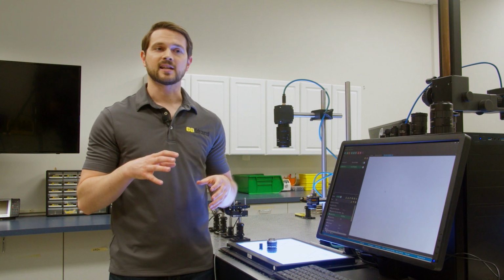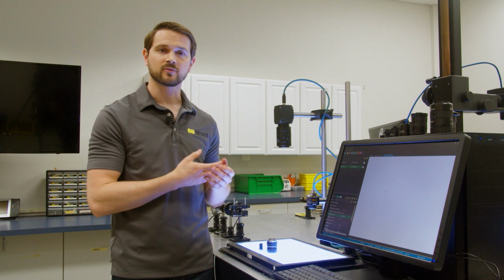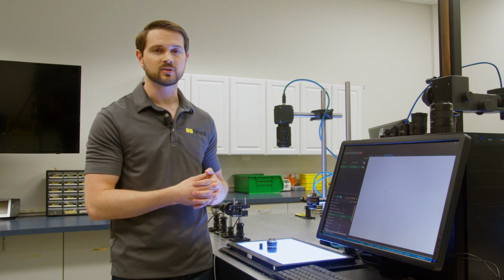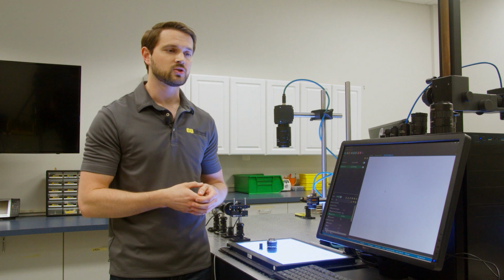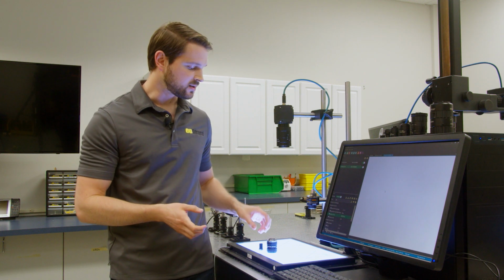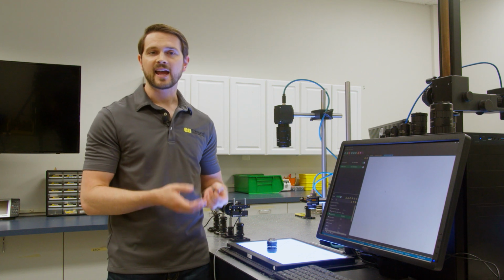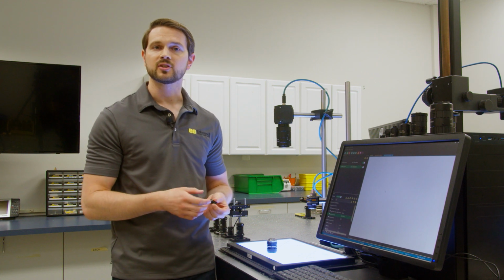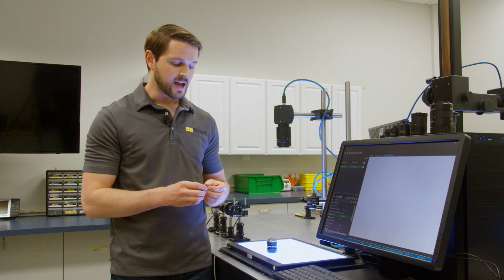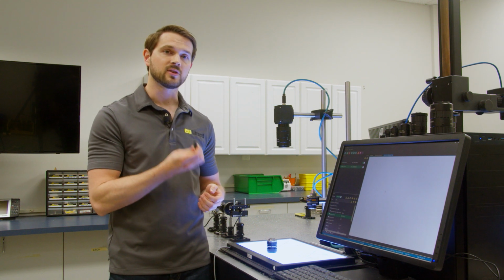It's actually an old notation that comes from imaging tubes. I'm not going to dive into those details; shoot us a question if you want to know more. But essentially, we look at the diagonal of the sensor, which in the case of a 1/2 inch is an 8 millimeter diagonal, and we match the lens to that diagonal.